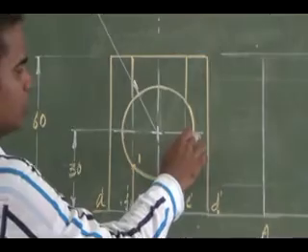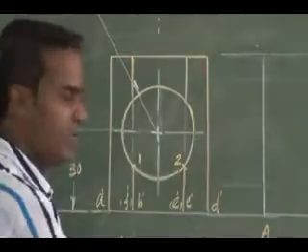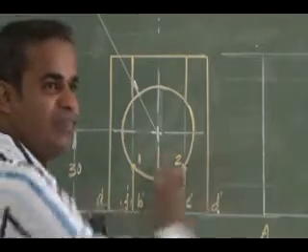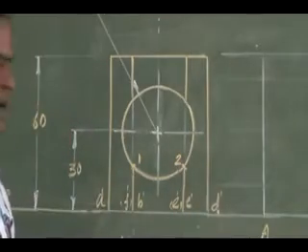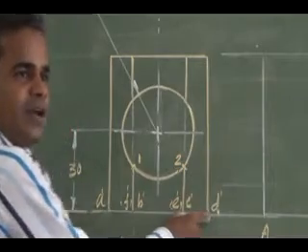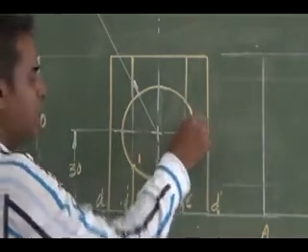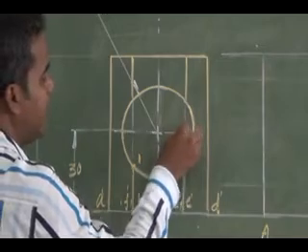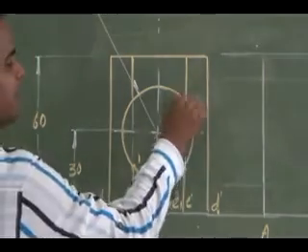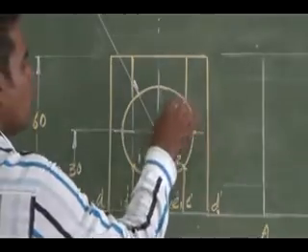Then it goes to a slant surface. This portion in the front view is a slant surface, not showing the true length of that base. At the extreme tangent location I am marking the cutting point as 3. Then it cuts the front vertical edge C, that is my cutting point 4.